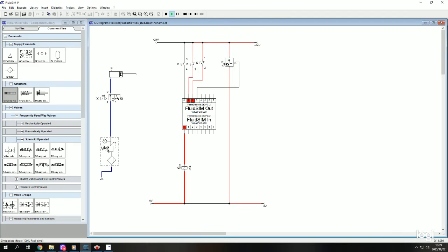The only difference is that this proximity sensor, it senses the rear end position. So the process remains the same. When we retract, we use this. We use this again. When we retract, we then use this emergency stop. And when we reset, it won't work because we've just inserted our emergency stop. So every time your piston rod goes back to its rear end position or retracted position, this proximity sensor will have this arrow showing that there's power because it's been activated.